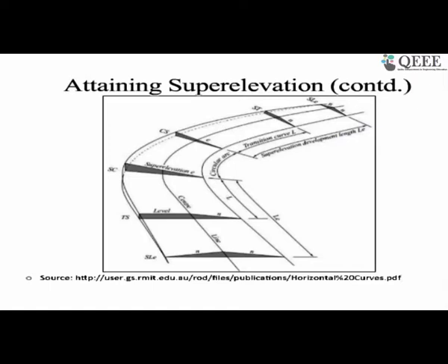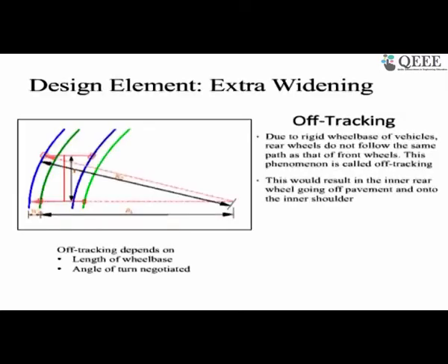And you have to always understand that at a rotary intersection the speed is quite low. We are not talking about speeds of 50 kmph and 100 kmph where we do need the super elevation. So at a lower speed, the camber itself or any slope which is going to help to drain off the water can be easily accommodated to whichever direction it is needed. So now let's move on to the next slide.